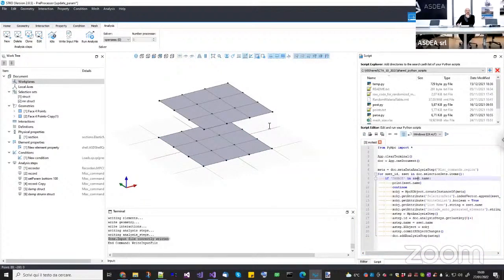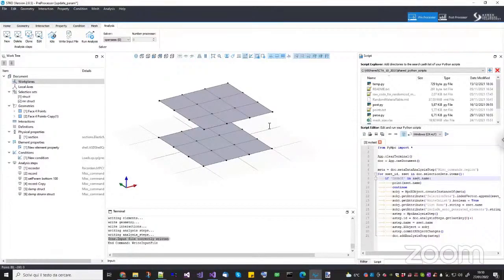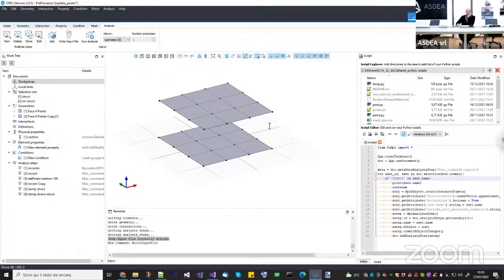What else? We are here. Pavan asks: how to model a pile with parameters like bending stiffness, base rotational stiffness, and yield bending moment. If I understood correctly, this is just how to model a beam with those parameters. In any case, you always need to create a bending stiffness. I don't understand the base rotational stiffness. What do you mean by it? I think you might mean to use a zero length element. Yeah, probably I was thinking about the zero length, saying that it is not completely fixed to the soil.